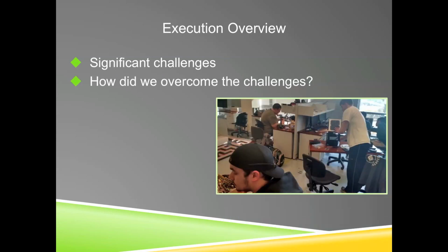The solutions to these challenges are that first we had to find the right combination of resistor and capacitor values to give us the correct range of 5 to 12 volts we were looking for. Then testing was done with a low frequency pulse width modulation, and the simulated DC voltage worked like a real DC signal as expected. Finally, for the problem with deciphering the data we were seeing, it was found that the first byte was the header byte, which told the server what type it was, and then the following array of bytes was the information. So the solution was easy, to write a function to identify the header byte and then store the actual information.